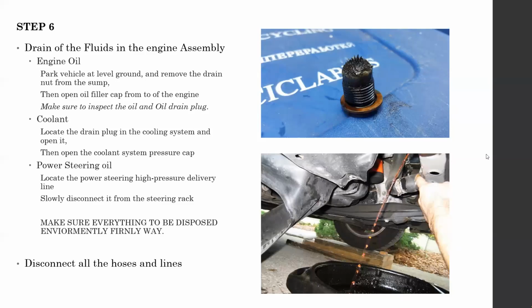So you can clean it without any trouble. But before you do, you have to find out why this metal is coming. It should not actually fill with metal. If there's metal, there's something wrong. If the oil drain plug has metal, check the engine oil also. If you can see small silver-colored particles, or a glitter effect in the engine oil, that means your engine is wearing out, also known as metal to metal surface rubbing.